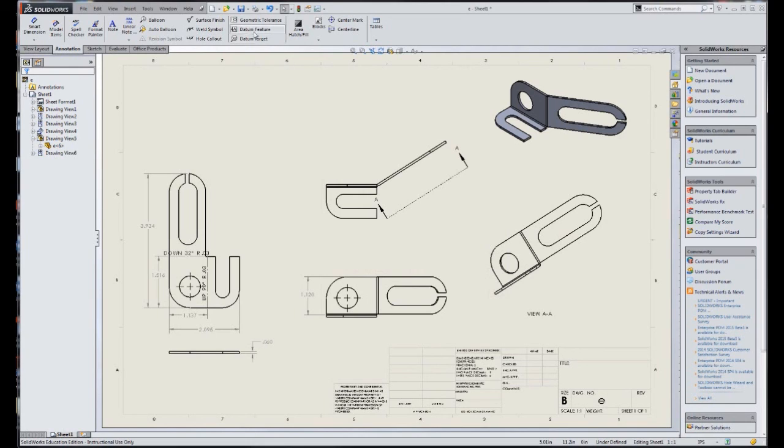All sheet metal drawings that you will be turning in for me must have a flat pattern. If they have bend marks, they must be dimensioned. They must have the overall dimension and the thickness. I don't worry about these interior details, the curve, the radii, because all that takes place on your general 3 or 4 view, however many view drawing you need. And that sums it up. The rest of this, you go through and you dimension as usual. Make sure all the dimensions that are there, you have size and location of all features.